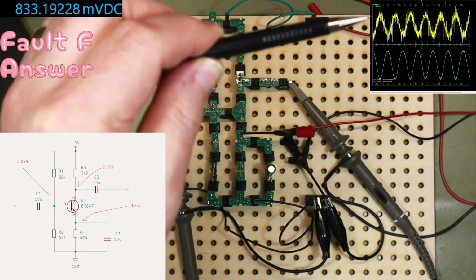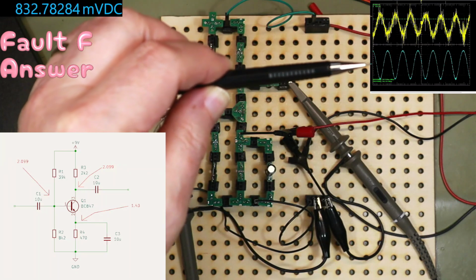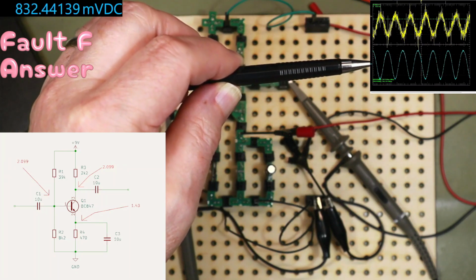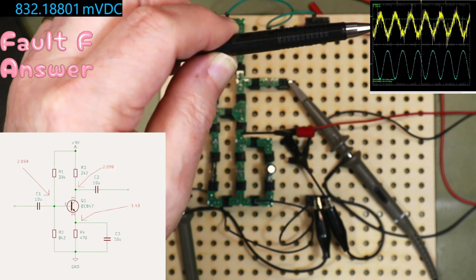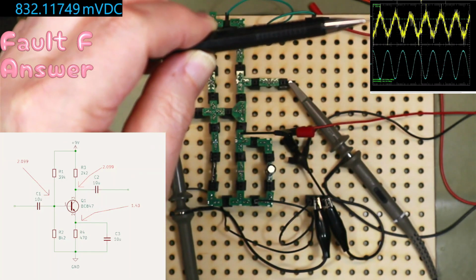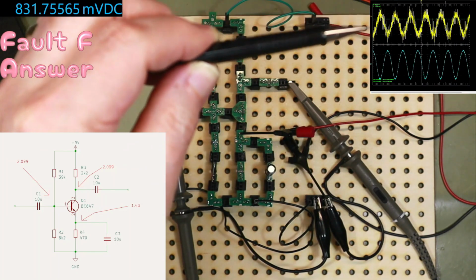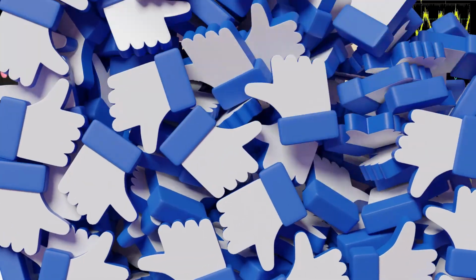It should be down here in the middle like it is here. You can just see the 0 volt marking there, so it should be swinging either side of that. But here you can see it's completely rubbish, and it's on AC, so it should be swinging either side of that, but it don't. So I wouldn't buy one of these scopes again, even if they offered it for free. Right, so that's that fault.